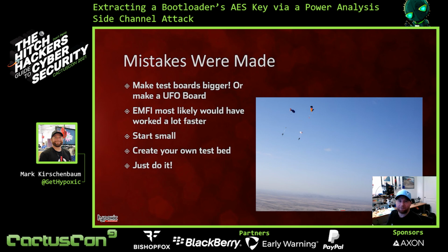EMFI would have done this a lot faster, and that's kind of like the way of the future. I think a lot of people are not doing power analysis side channel attacks as much anymore because these EMFIs or even laser attacks are really powerful and really quick. Again, start small, make your mock-up, learn all the samples on the NewAE ChipWhisperer ecosystem, run through all that stuff so you really understand it. And like I said, create your own mock-up there. And obviously, like any of this stuff, you just need to do it. You just need to run with it and try it out yourself and see how it works.